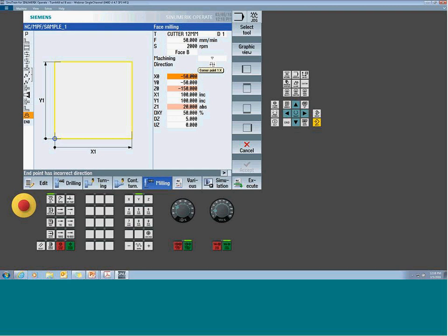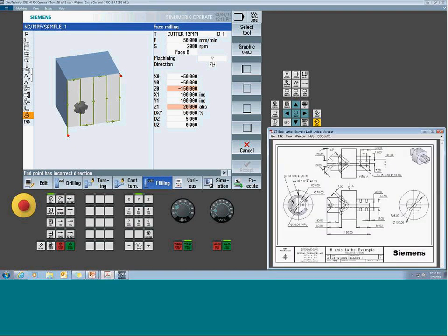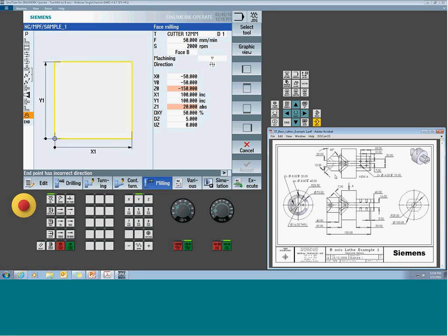We're going to choose our amount of facing. So the center of this feature is 0, 0. So here, how much in my X? Well, I know that 10 millimeters gets me from the center of the bolt hole pattern, which probably is the center of the feature, out. So I need at least 20 mil, and there's 0.